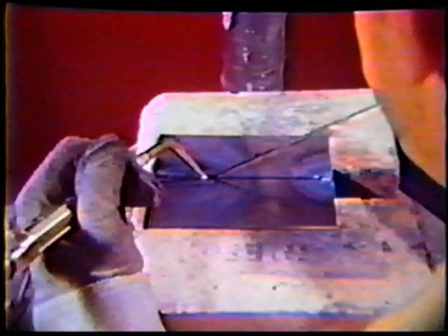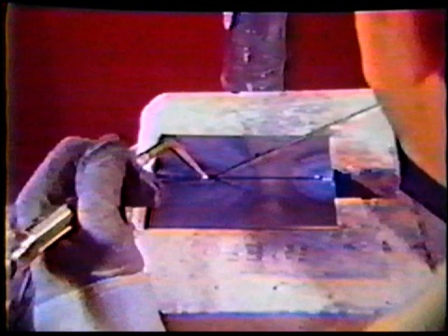Instructions in this course are related to right-handed welders. For left-handed welders, positions and angles should be reversed. For example, in forehand welding, the right-handed welder holds the torch in his right hand at the right end of the joint and travels toward the left, adding filler metal with the left hand. The left-handed welder would hold the torch in the left hand, filler rod in the right, and would travel left to right.